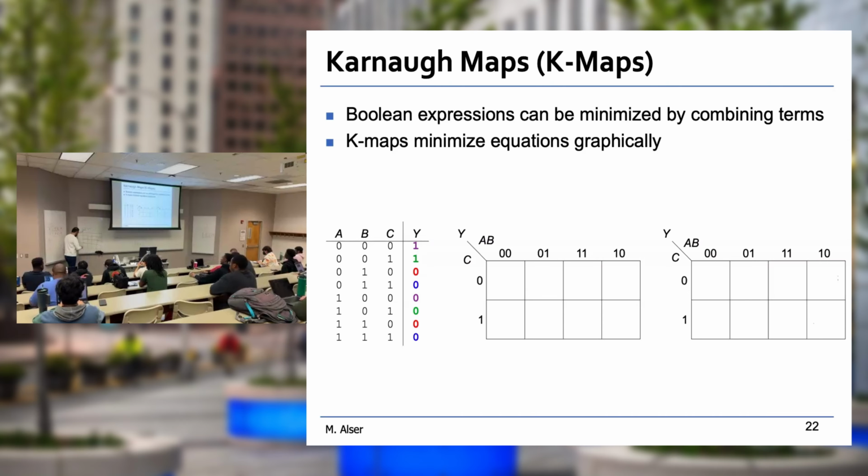All right? Now, let's annotate it. We said we go with 0, 0, right? 0, 1, and then 1, 1, and then 1, 0. If you ever forget, ask yourself how we could move from one box to another box with only one move. And a move here means changing only 1 bit value. They're not allowed to change 2 bit values. Any box to another box, change only 1 bit value.